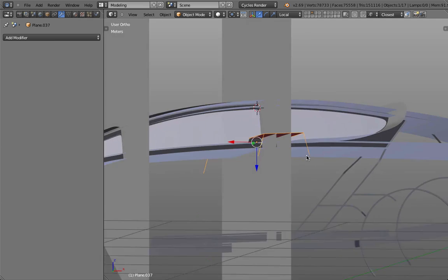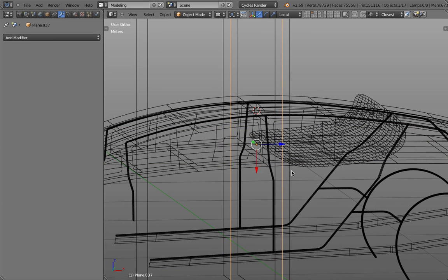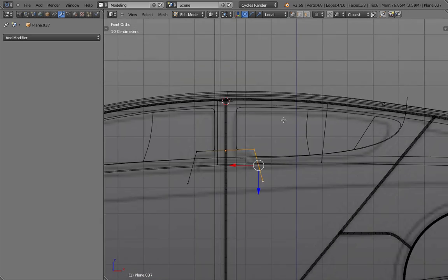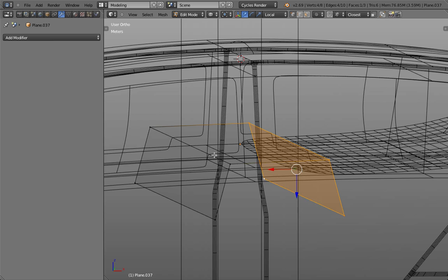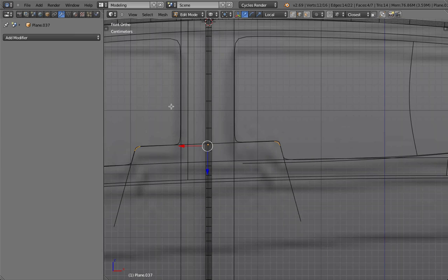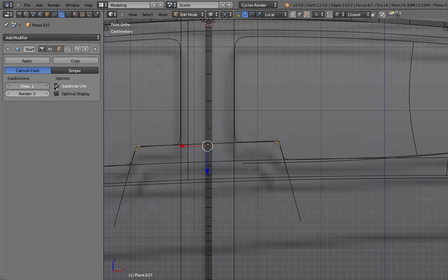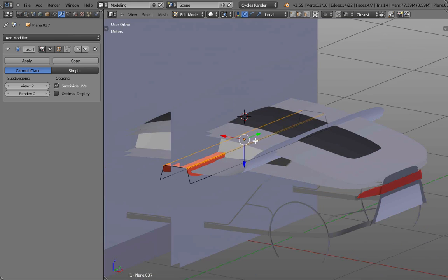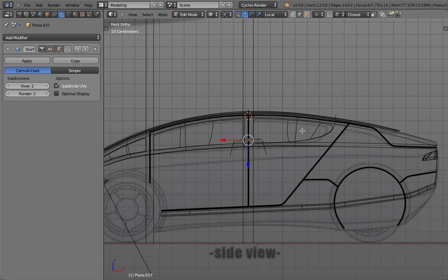Okay. And, oh, by accident I deleted some faces. Okay, I have to put those faces back in. So very simple rectangular blocks. And maybe I put in a little bit of edge rounding into those. So I bevel it, move my mouse wheel maybe once, so I have kind of like a small fillet, turn on the subsurface. And yeah, let's say this is okay, and we can leave it this way. Okay, select everything, Control N to flip all the normals to the correct side.